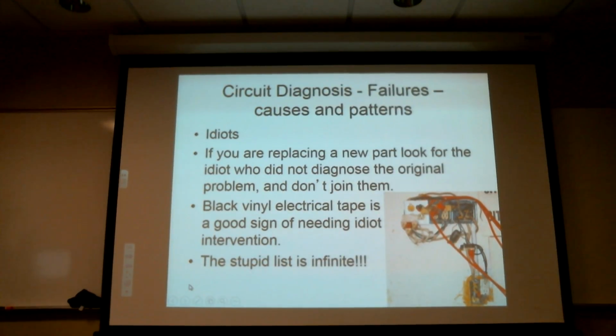But that's the kind of stuff that at some level you guys as mechanics have to say, I'm not going to accept that. If I see stuff like that on an airplane, you know who I'm going to call? You guys know exactly who I'm going to call. I'll call up the FAA. Hopefully that would never be on an airplane, but I've seen stuff on an airplane. Somebody had gone in and done some structural cutting on the doorpost of the 210. They had replaced a section and cut through the entire structural element of the doorpost, and then covered it with sheet metal so you couldn't see it until you pulled the paneling up. That's a Sawzall cut through it. And it destroyed the airplane. When I called the FAA, they looked at it and they went after it.